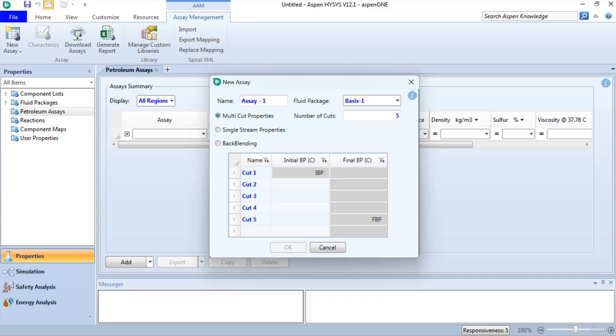The input products are typically defined in commercial distillations that have a significant overlap across products. Backblending creates an assay from these characterized feed assays by defining data and conditions for their outlet mixture. Backblending creates an assay from these overlapping measurements that can be used as a HYSYS petroleum refining feed stream.